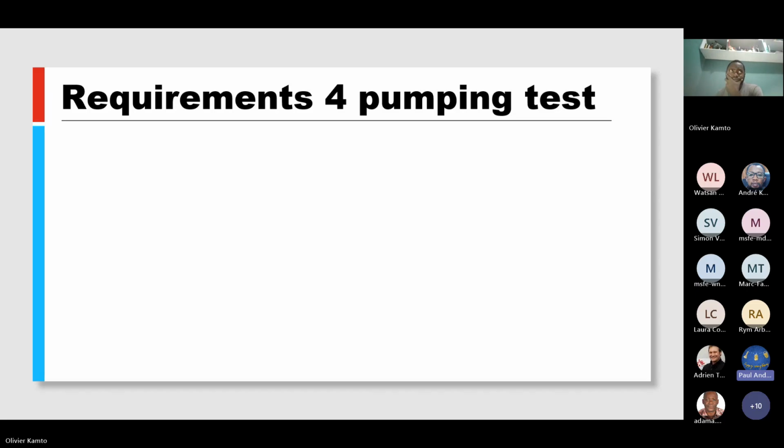Okay. Ben says dip meter in the chat. Okay. Anything else you think is required in a pump test? A pump comes up for a pumping test, which is quite good. Very important, yes. Stopwatch, water level indicator, pump and generator. Ben wants a clock or timing. Yep. Okay. Coro wants a generator. Flow meter, logging sheets. Yeah, logging sheet comes up a couple of times, which is good.